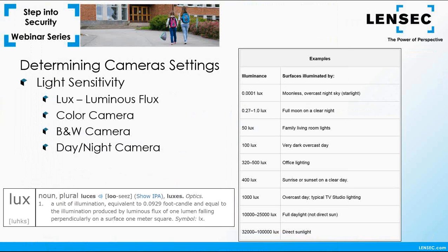Color cameras are not very sensitive in low light by their very nature. They don't pick up light well within the infrared spectrum. This helps to maintain less glare and also improve color clarity of the image. Black and white cameras, however, have been a workhorse for low light imaging. The black and white camera can pick up the infrared light spectrum and see better in areas where lighting is poor. They can often pick up details of a scene when a color camera is only seeing black.